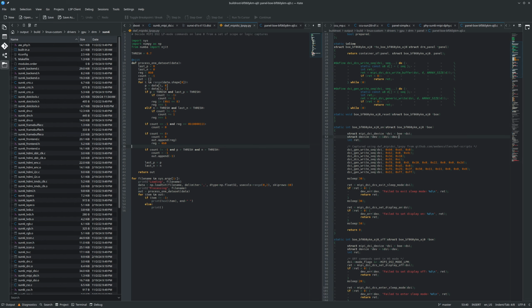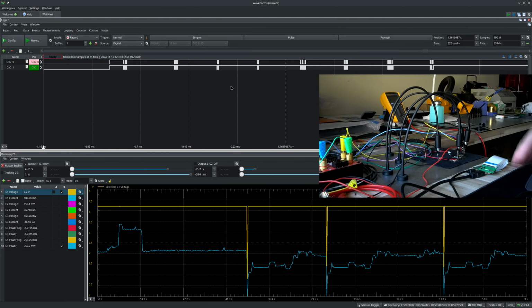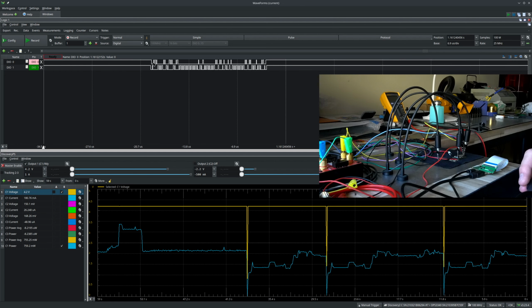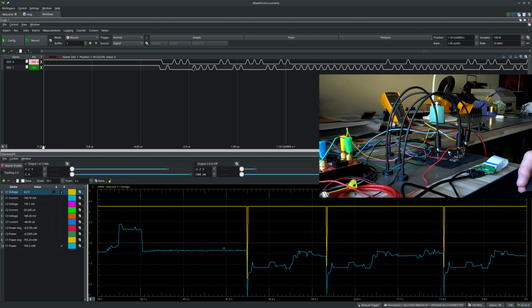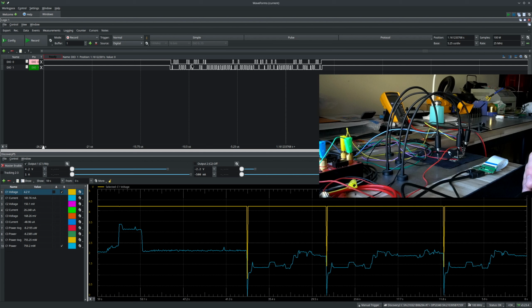And yes, if you had a logic analyzer, for instance like the Discovery 3 or something that only handles 3.3 volt inputs, of course you just have to put some level shifters in front of it. I suppose even with a microcontroller like an Arduino and some level shifters, you could pretty easily receive this. But yeah, the Discovery 2 makes it really easy with the 1.8V analog input, or any other analyzer that can handle these input levels. Hopefully you might find that interesting, and see you later.